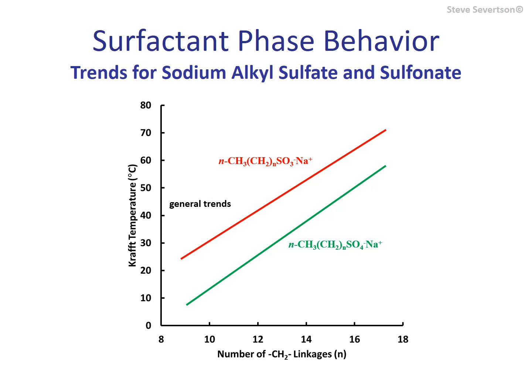In general, these curves demonstrate an important point regarding the selection of surfactants. As discussed, the more hydrophobic ionic species provide the greater efficiencies. This would indicate that the proper choice between surfactants is always those with the larger hydrophobe. However, it can be seen that phase behavior must also be taken into account when formulating complex systems such as emulsions and foams. If a surfactant is used below its Krafft temperature, little can be introduced to the system, and as a result, the surfactant provides little surface coverage and poor performance.